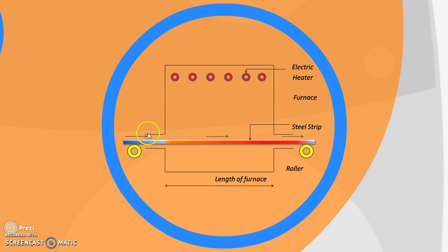There is one heat treatment process, known as annealing, which can restore these mechanical properties. In the annealing process, we heat the material to around 600 to 700 degrees Celsius, and then we cool that material with atmospheric air, from a temperature of 700. The strip which came from the rolling operation will enter the furnace.